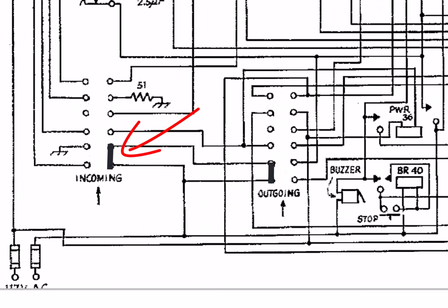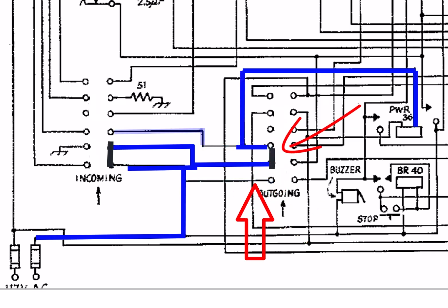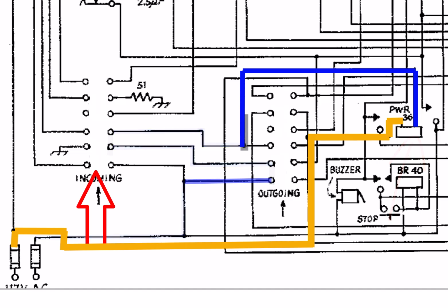And let's look at the bottom shorting block on both of these buttons. Now, all of this cross-connecting between the 2 buttons serves the same purpose. When neither button is pressed, this line input goes nowhere but to the bottom contacts. But these are mechanically wired as an OR device, so if either button is pressed, then this line voltage is applied to one terminal of this main power relay. The other terminal of that relay coil is always connected to the other line input.